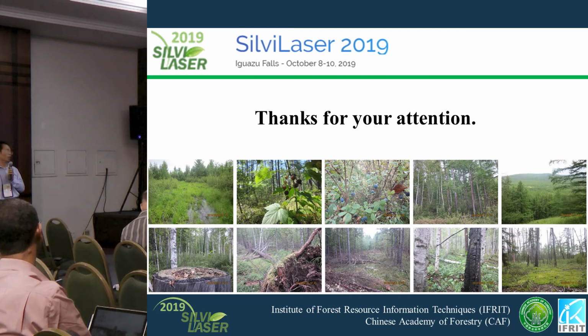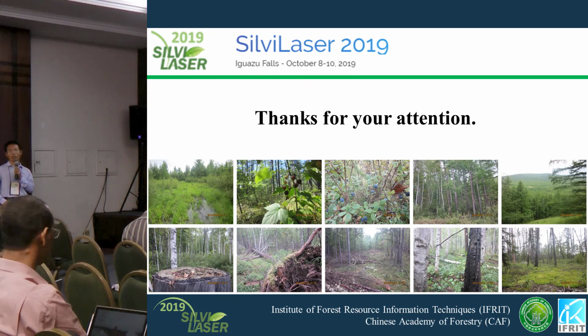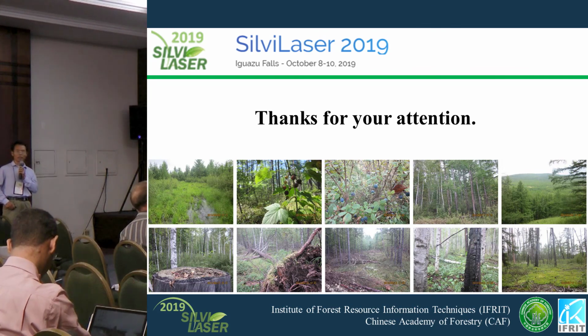In some cases, especially when flying a normal UAV, if the flight height is close to the maximum range, for example if the LiDAR has a 1,000 meter range and you fly at about 900 or 800, this phenomenon should be considered, because with the slant distance and light scattering, the phenomenon will obviously exist, so it should be corrected when you calculate canopy cover.